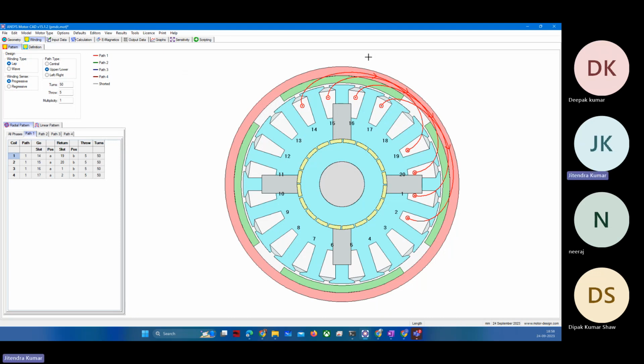And when it rotates, it has to go through all the varying magnetic field. When it goes through the varying magnetic field, your flux is no longer DC. Did you get this point? It may take a while to grasp these things, but that's the whole thing.